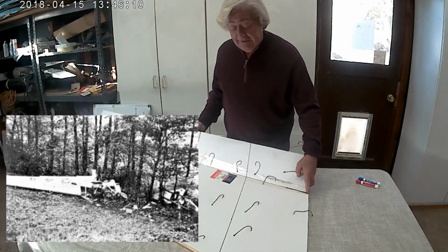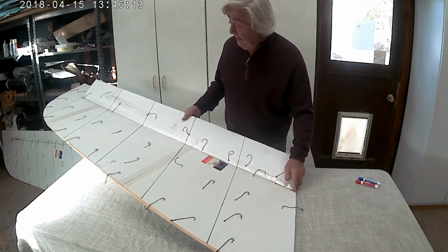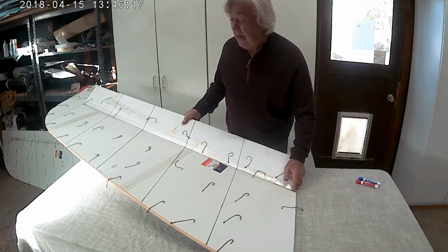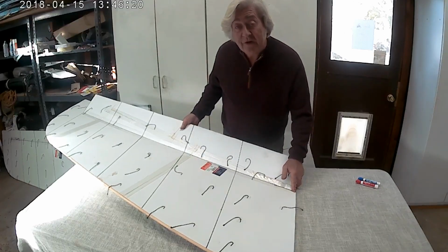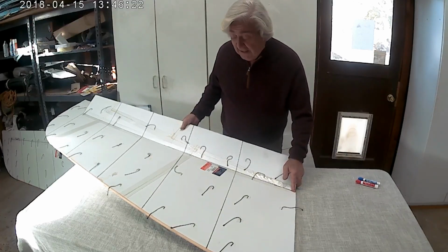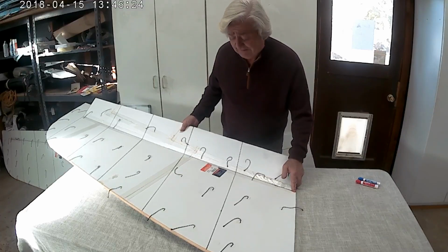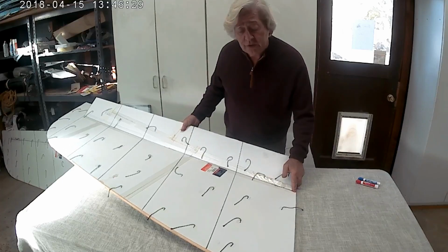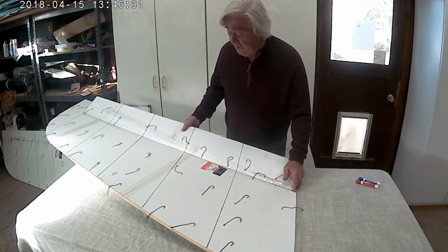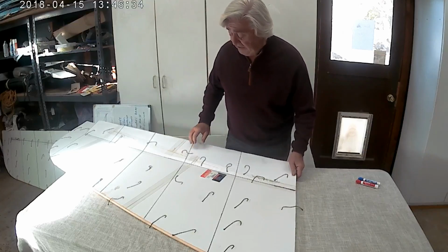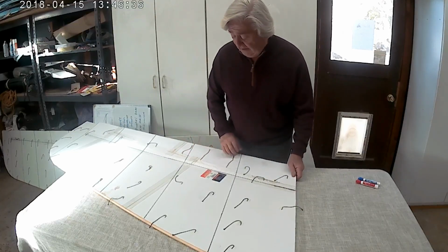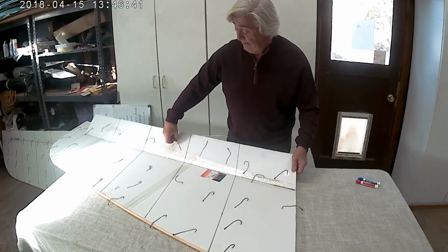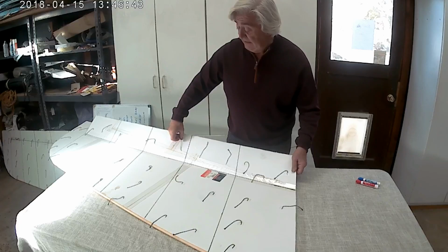So, barn doors. They can work pretty good on models, and I thought about using them on my current wing design, and I tested it out on various versions of models of mine, and found sometimes it works, sometimes it doesn't. And it wasn't particularly clear why one worked over another design. But when they do work, they really help stop the spanwise flow. These guys, instead of being way out like this, they'll be a little less, somewhere around in here.